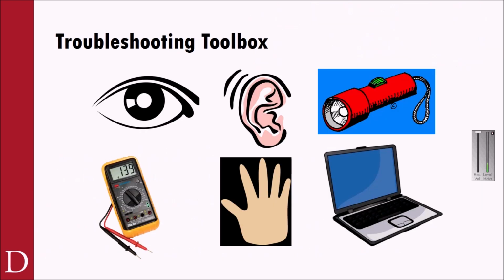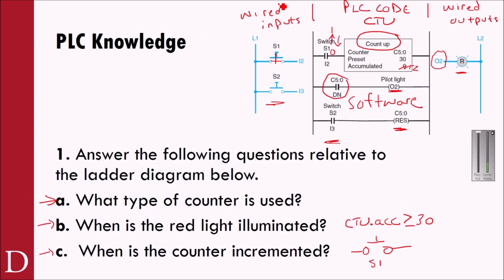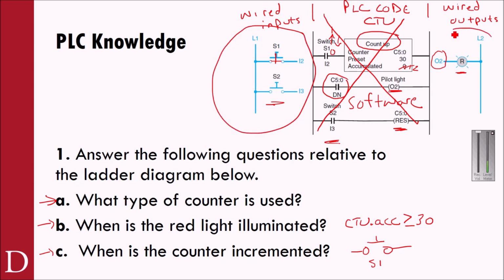All right, so let's get into how we troubleshoot. Because I'll be completely honest with you, when we look at this package here, assuming the machine is working correctly, your problem is probably not going to reside in the software. So typically the prints are going to give me the wired up inputs and outputs. The reason those are important is, wires can come loose, they can vibrate loose, or inline fuses can blow, or somebody may bump into a connector shell, an Amphenol or quick disconnect going into a control cabinet, and that may break a pin.